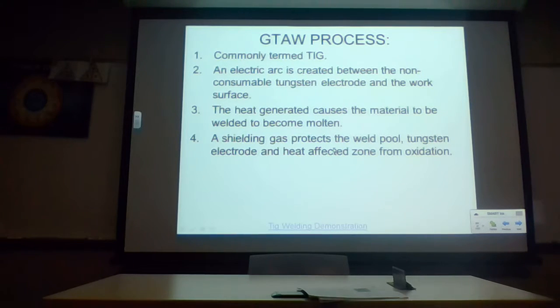So in some respects, I guess it's kind of similar to oxyacetylene welding, but it also is an electric arc process. So the electrode is not consumed. It's not like stick welding where the electrode is actually consumed. The electrode only carries current. And you're going to have a reinforcing rod that builds up the weld bead, just like you use in oxyacetylene welding.